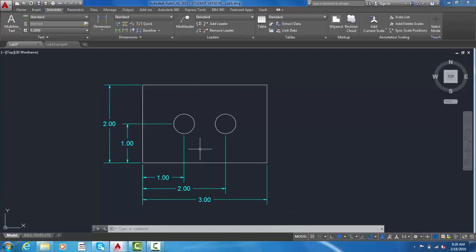It's also considered poor practice to have your dimension lines, your extension lines, these are extension lines, crossing your part geometry. You want to minimize that wherever you can. So again, we can use grips to do that. I'm going to simply grab this dimension, I'm going to grab this grip, and I'm going to drag it back down to be on this line. Note that I'm using my object snap. I'm finding the intersection of the current extension line and my object line so that my dimension